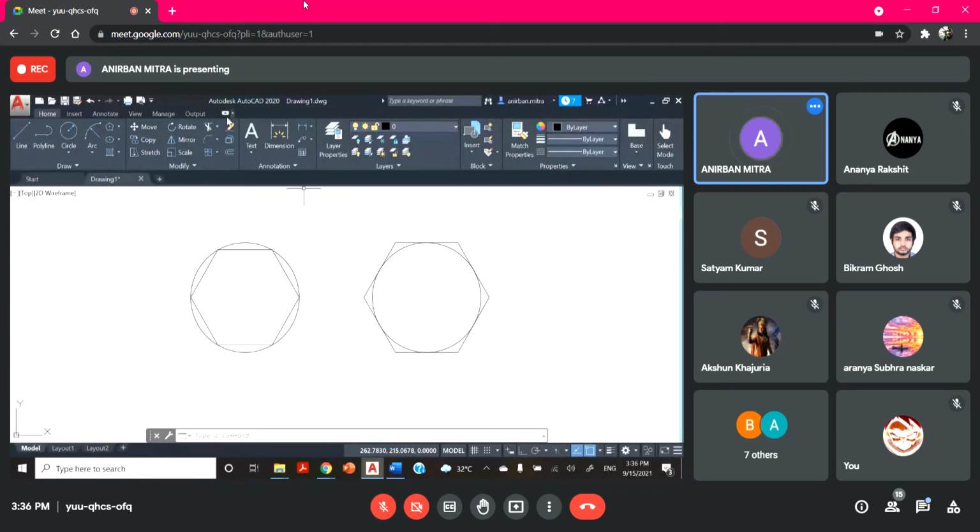The same option works for the rectangle as well. Let's say I have created this rectangle. It is coming in this skewed or rotated way because it already has that 45-degree angle as default. If you want to change it, after you have given the first point, go to rotation, that means R, and make it 0.